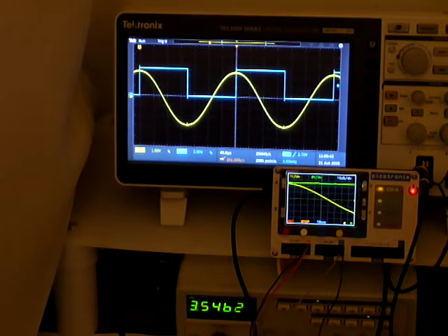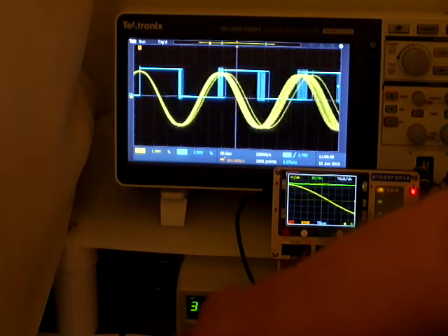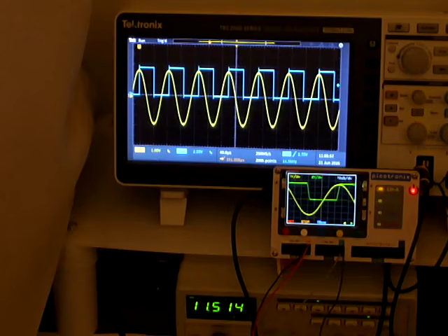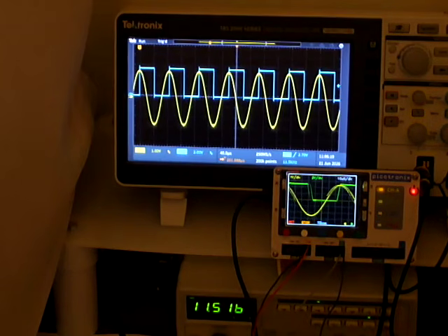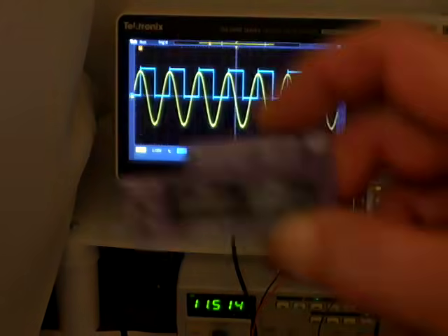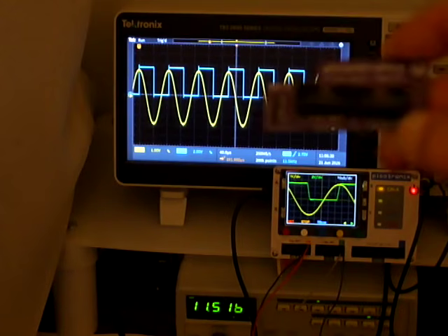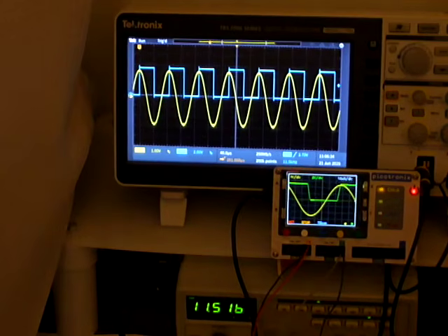For the base level instrument, at the moment we're stopping at 10 microseconds per division. Later on we will activate ESR, which is effective sample rate detection, and probably move up so we can look at signals up to about a megahertz. But the other solution is that Picotronix is expandable, so on that connector on the right we can plug in a much faster ADC. So we have a board which you see there. That board plugs in and it gives you a logic analyzer, and also it's got a 100 megasample ADC on it.